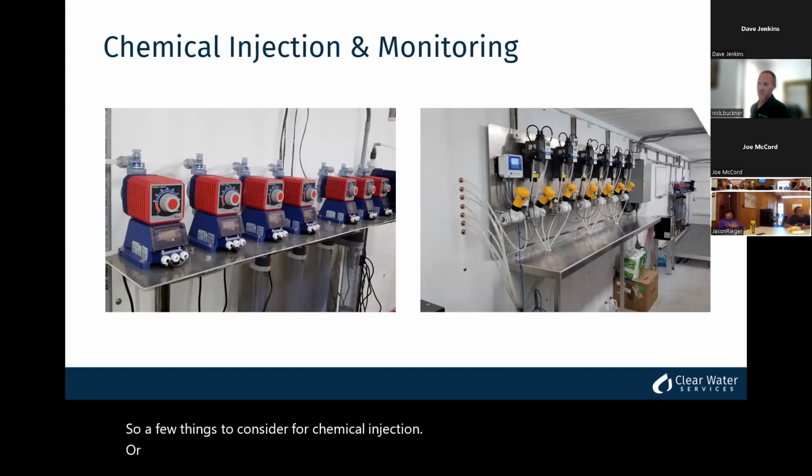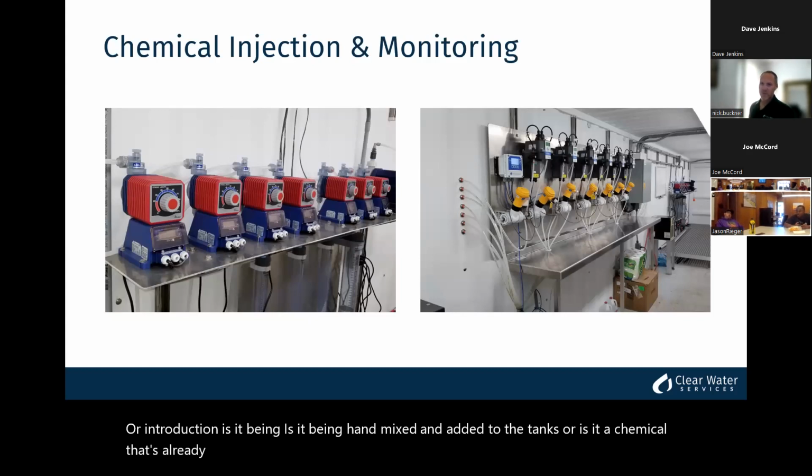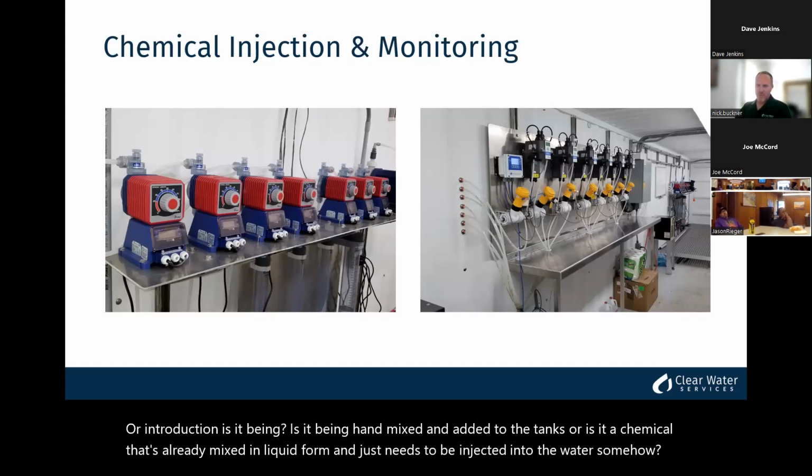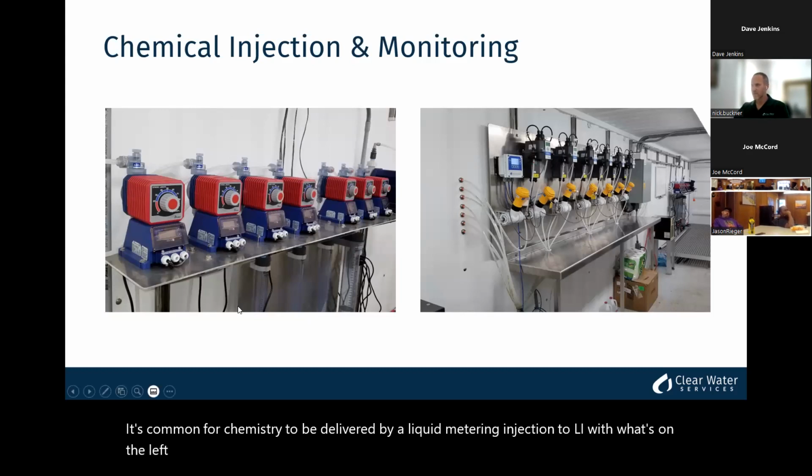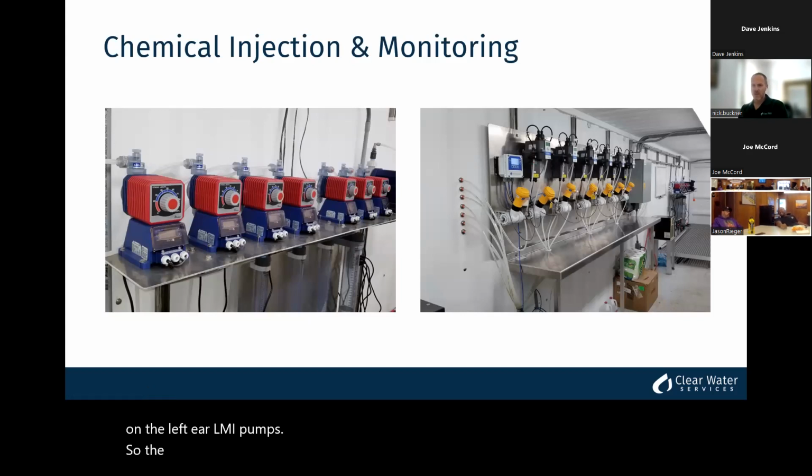Is it being hand mixed and added to the tank, or is it a chemical that's already mixed in liquid form and just needs to be injected into the water somehow? It's common for chemistry to be delivered by a liquid metering injection, the LMI. That's what's on the left here, LMI pumps. So the pump can regulate the speed and the amount of chemistry that's getting dosed into the water.